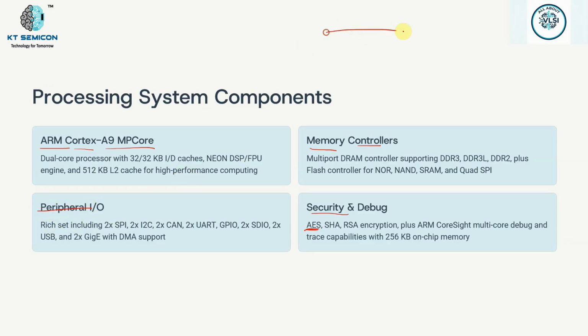Okay, so let's say this is nothing but my processor and this is nothing but my PL. Let us come back to PL later, but we are going to focus upon this PS. Why I'm going to focus upon this PS is that the PS is going to have these controllers. So these are all my controllers: UART, GPIO, SDIO. These are all the IPs which are present.